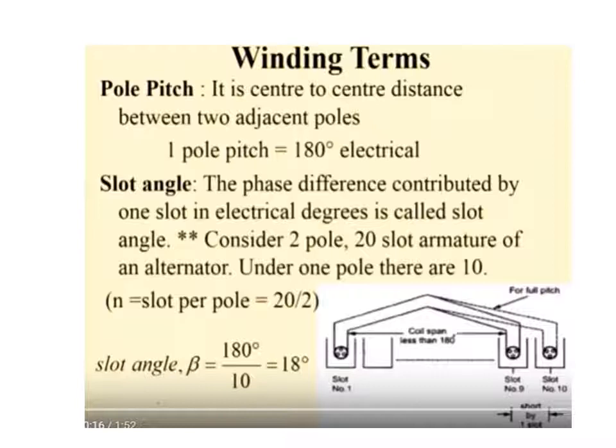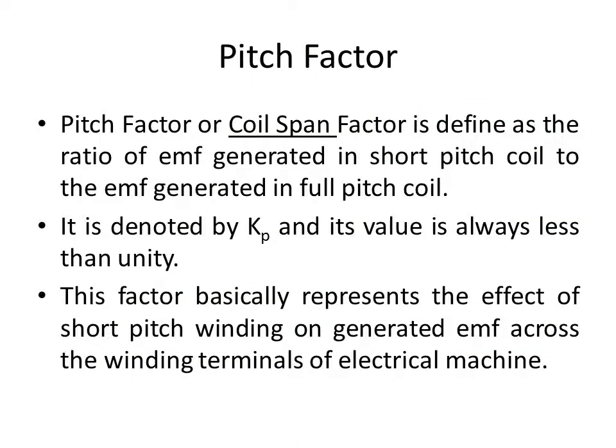You need to draw the diagram. Along with the diagram, you need to explain the differences between the full pitch coil and the short pitch coil. Pitch factor, or coil span factor, is defined as the ratio of EMF generated in the short pitch coil to the EMF generated in the full pitch coil.